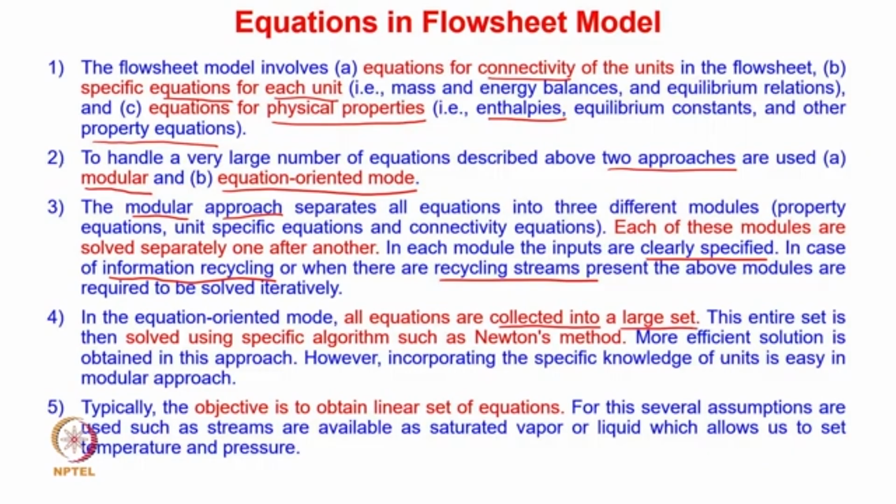All these equations, with respect to connectivity of units, unit specific equations, and even the equations with respect to properties, are collected in a large set, and this entire set is then solved using specific algorithms, like Newton's method. Clearly this second approach is more efficient, because you are looking at all the equations together, and therefore a more efficient solution can be obtained.